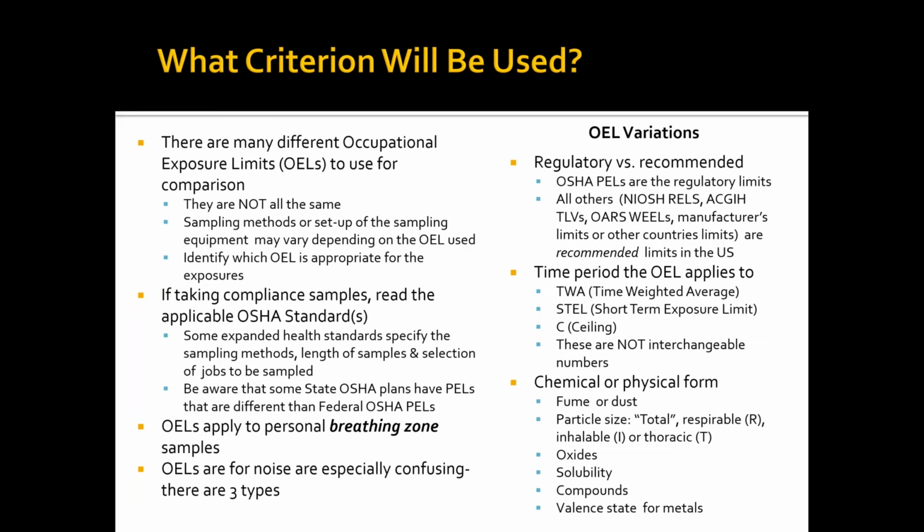If there's a direct reading instrument that can instantaneously measure the substance, that's my preferred method for doing ceiling limit exposure assessments. But a lot of things don't have that. And so you're stuck with, what do I do now? And the answer, in my opinion, is that you sample for the shortest amount of time that will get you above the detection limits for the method. So sometimes with chemicals, that may be a 30 to 50-minute time period. It's not perfect, but in the absence of a direct reading instrument, you really don't have another choice.